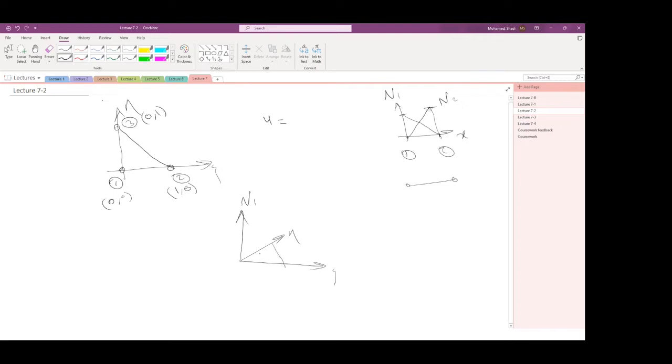This is our triangular element. This is the first node, the second node, and the third node. I'll put the numbers 2 and 3 here so you can see them in relation to these nodes. The first shape function is 1 at the first node and drops to 0 at the second and third nodes. So this is the triangle that is going to happen.